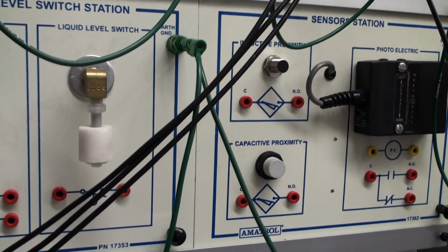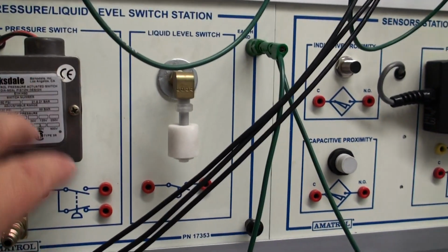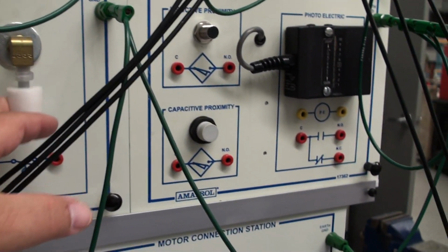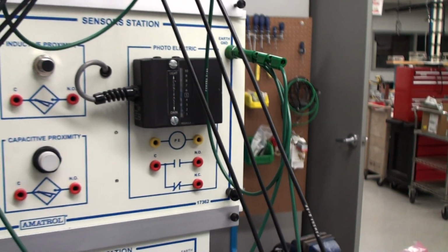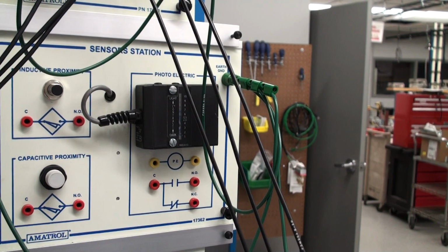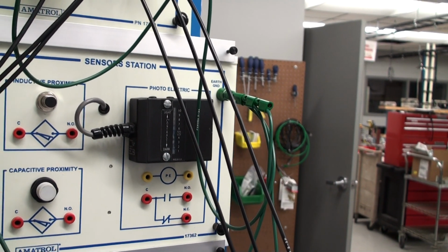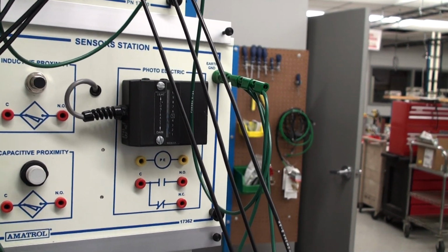All kinds of different switches, including pressure switches, level switches, basically a float switch. As the air pressure changes here, whoops, I'm out of the frame. As the air pressure changes here, then the switch can either open or close. Same is true with the float. Down here we've got some capacitive, inductive proxies and photoelectrics. Those are sensors that can be made without physically having to touch the device,